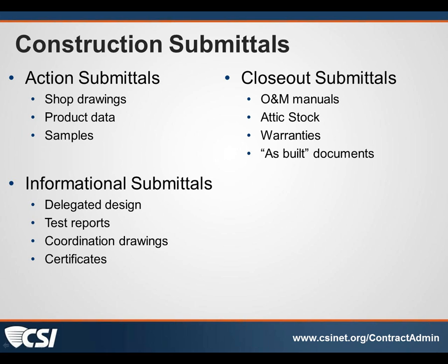Let me address the comments that we got, Jim. Kevin O'Brien again is referring to the EJCDC document C700. He says that document says that the engineer is to approve delegated design submittals for selected items only. He says his firm, because they use EJCDC documents, lists delegated design submittals as action submittals, which is different than AIA documents.